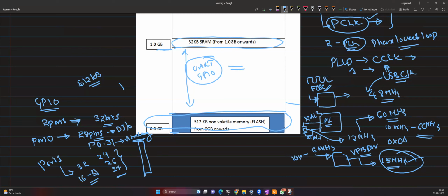In port 0, how many pins are available for use? 28 plus 1, that is 29, since 3 pins are not available. So here in port 1, 16 pins are available. 16 plus 29: in total, in the LPC2148, 45 pins are available for use.